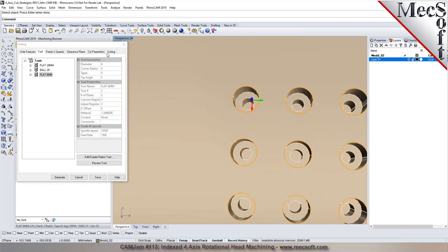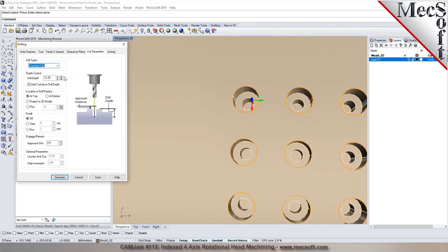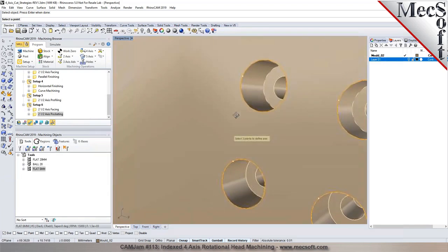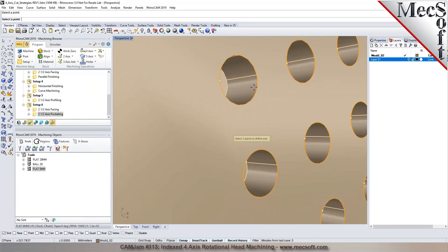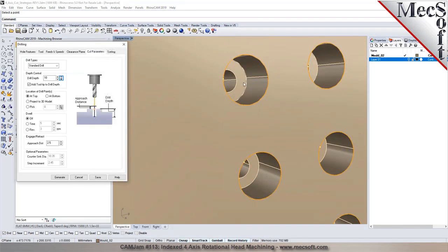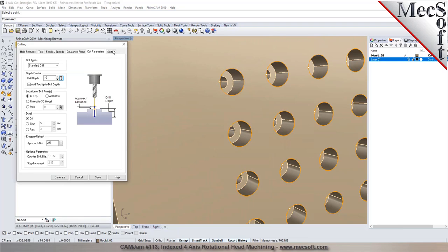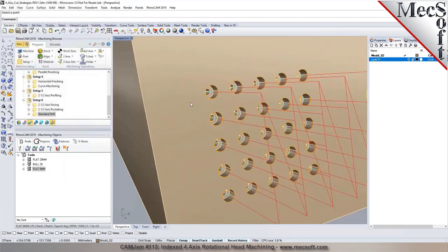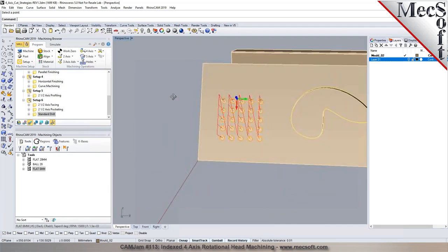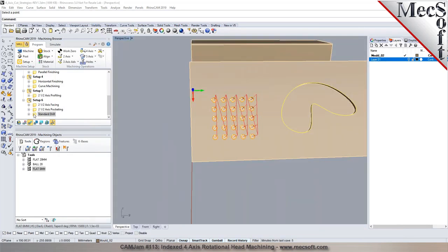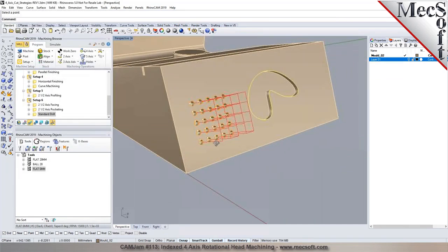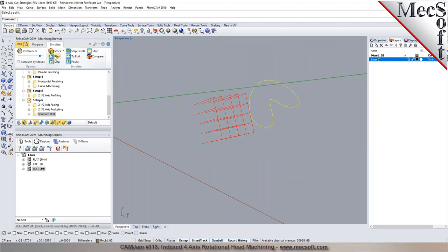And I'm going to go specify my cutting parameters in here. Pick the depth. So I want to go from here. I can pick a point, a reference, and go down to this one. And then you can specify how do you want to sort it. Go directional sort. So you want to minimize the number of transfers and retracts. And you can do a zig or zigzag for the cut pattern. So that gives you a drill operation.